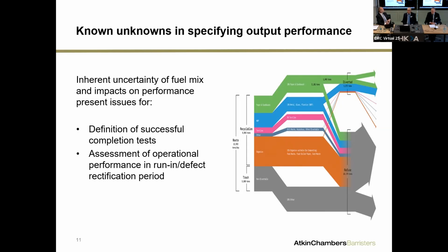What you'll see, not very easy to see, is in the very top, the very small bit, is diverted waste. That is what Trevor was talking about, of these diverted waste, cardboard, glass, being taken away and moved and then recycled. And you can see, in New York, and I think it's probably as true about many other countries, the vast majority of refuse waste goes into the big grey section at the bottom, which is what you're going to do with the remainder, how you're going to use it, incinerate it. If you're incinerating it, what you've got is a series of different fuel types, all with different heat outputs, shoved into a furnace all together, which produce vastly different, unpredictable heat outputs.